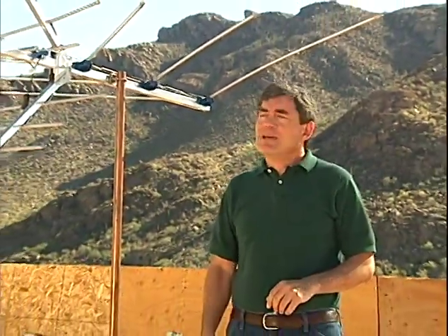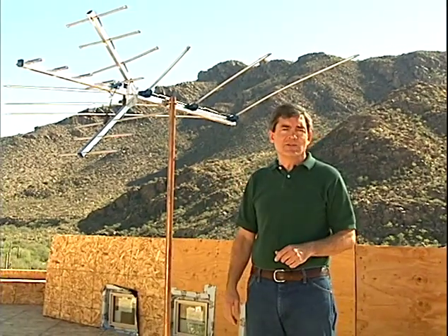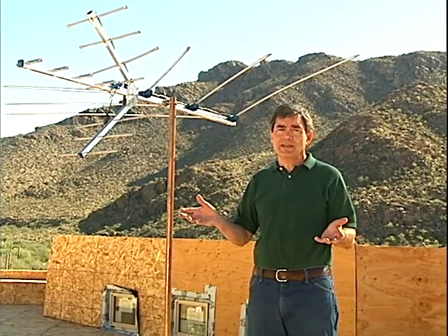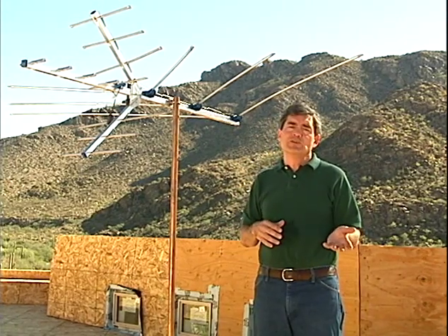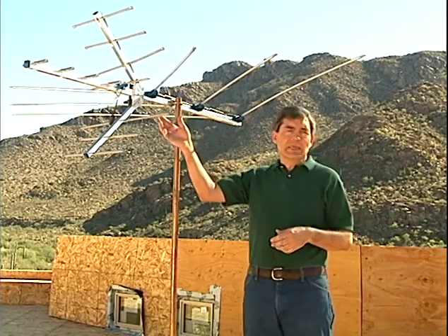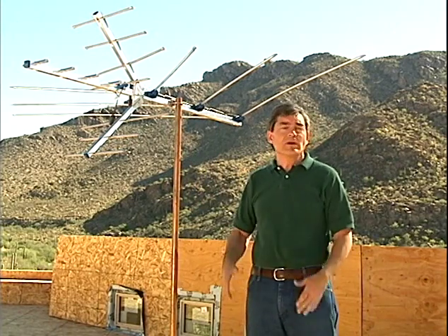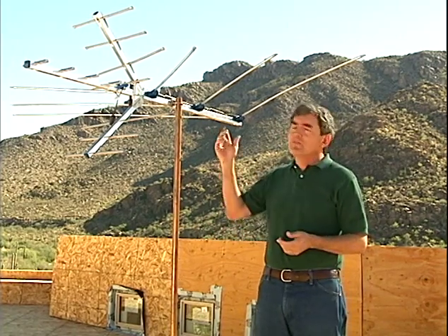Now, there are a couple of myths about antennas that we need to dispel right away. First, that you need some kind of special antenna to receive digital broadcasts or digital TV. In fact, all broadcasts are analog signals. The DTV refers to the information or the content of the broadcast signal, or the broadcast carrier as it's called. All broadcast signals are the same, and any antenna is perfectly capable of receiving traditional analog or digital broadcasts. Now, broadcasting digital content does have certain advantages and can influence the selection of an antenna, and we'll talk more about that in part 2.